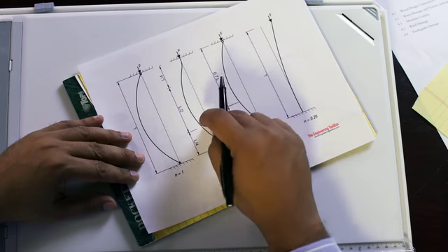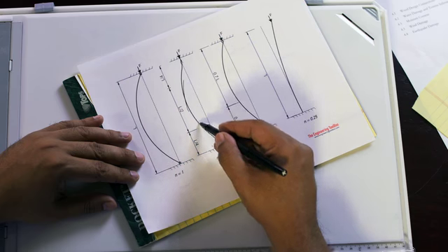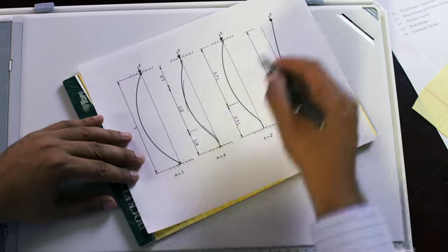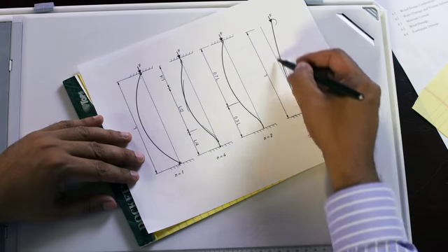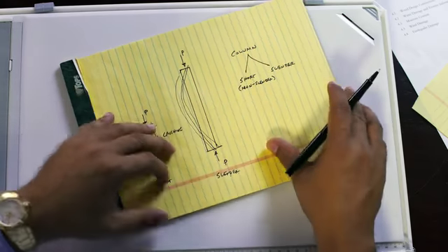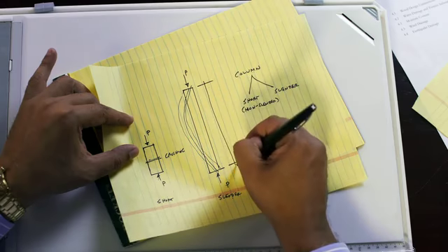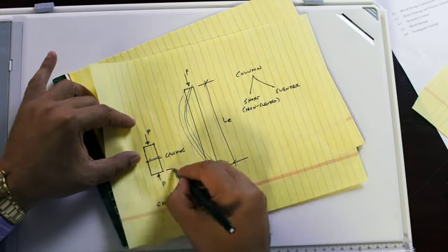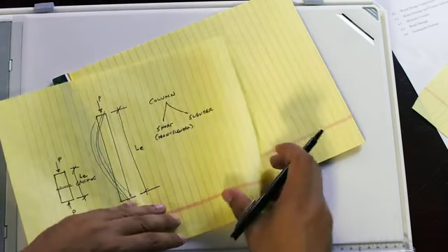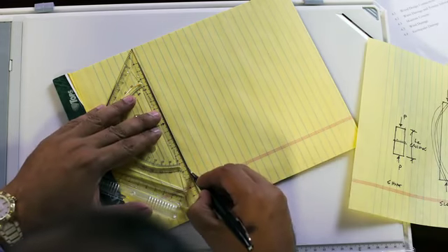So a slender column which has its rotation fixed at two ends will develop a buckling curve that looks like this. If it's pinned at two ends, it'll develop this type of buckling curve. If it's not fixed at one end, it'll have this type of buckling curve. So the capacity, if you do the design calculations on this and you graph this length here, which we call the effective length, if you graph the axial load capacity versus the effective length, the graph will look something like this.